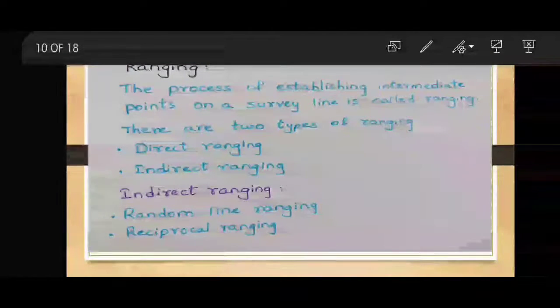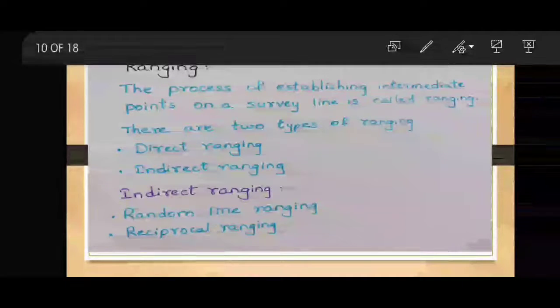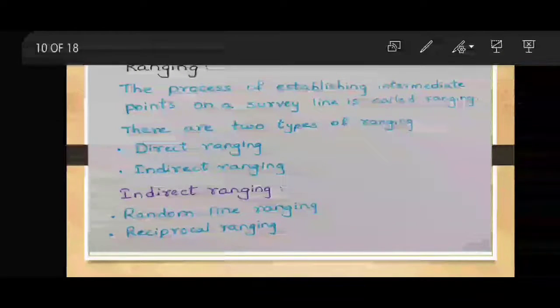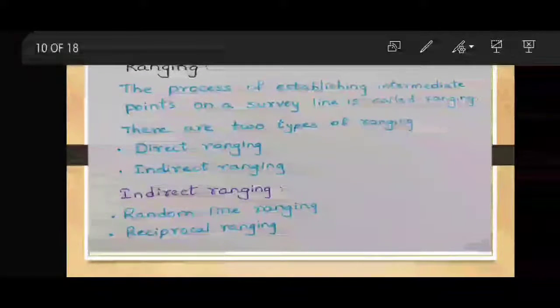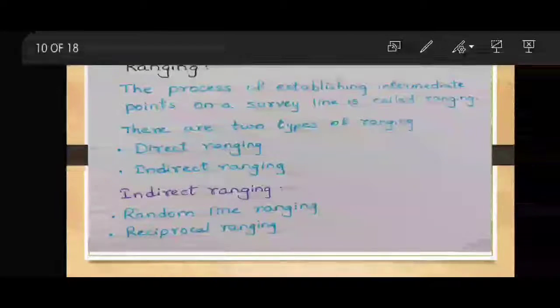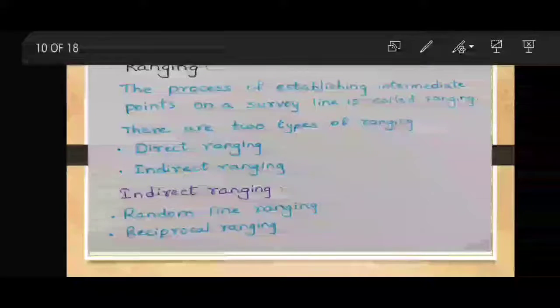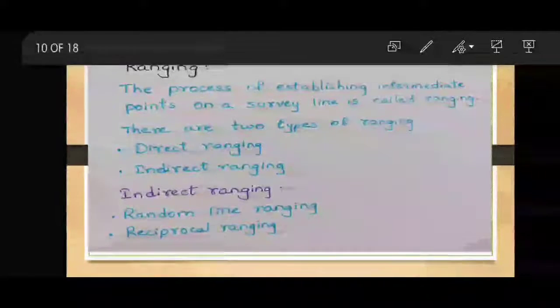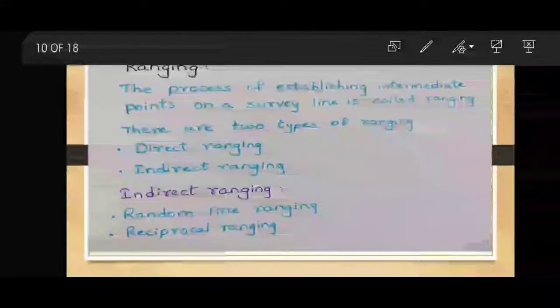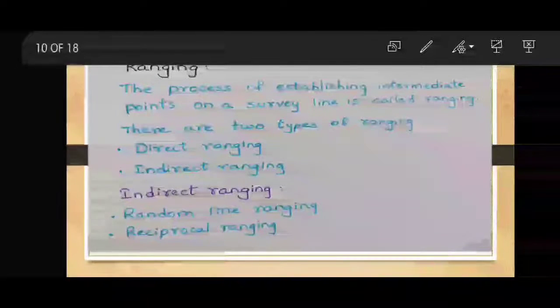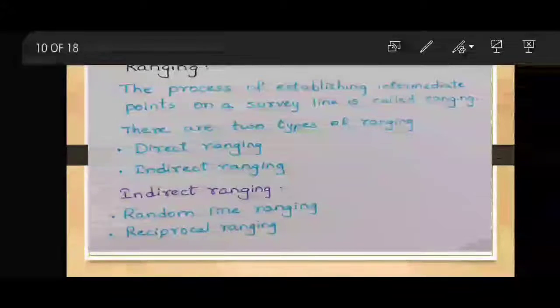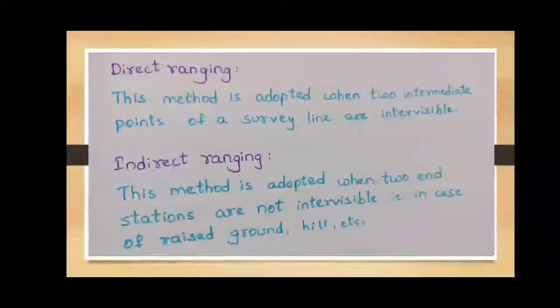For example, a rapid sweep with the right hand signifies to move rapidly to the right. A slow sweep with the right hand signifies move slowly to the right. Both hands above head and slowly brought down signifies that the fixing up of the ranging rod is correct. Left arm up and move to the left signifies plumb the rod to the left. Finally, both arms extended forward horizontally and the hands depressed briskly signifies to fix up the ranging rod.